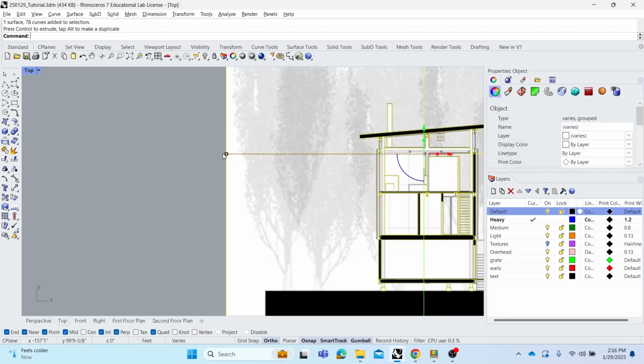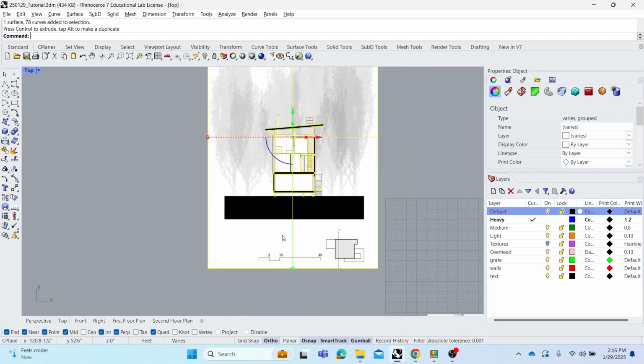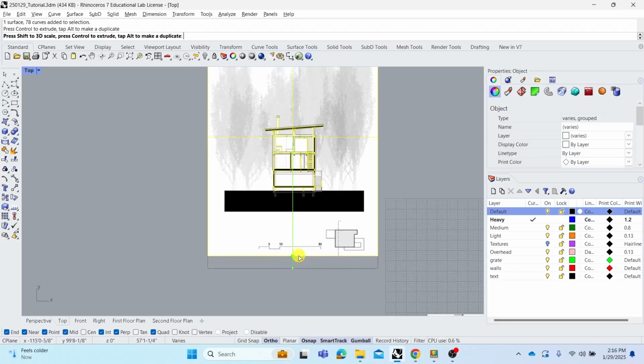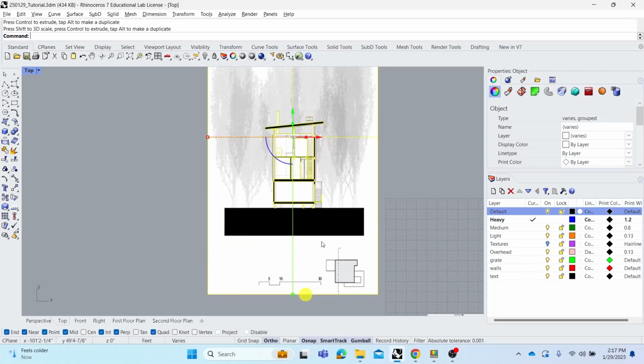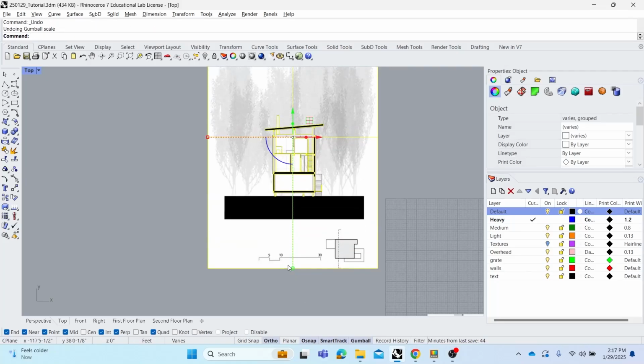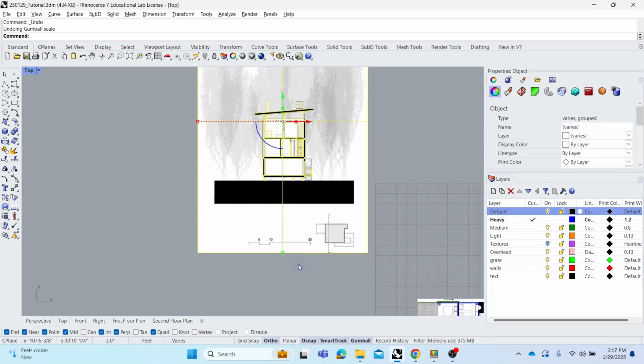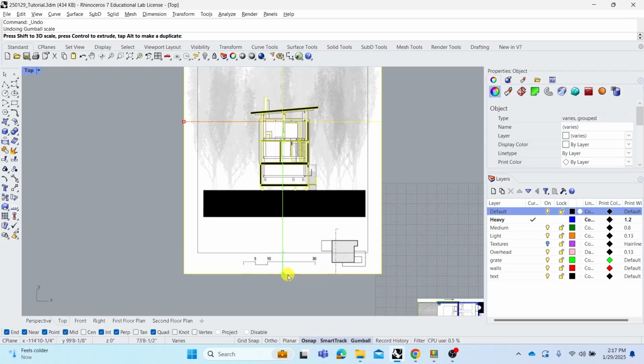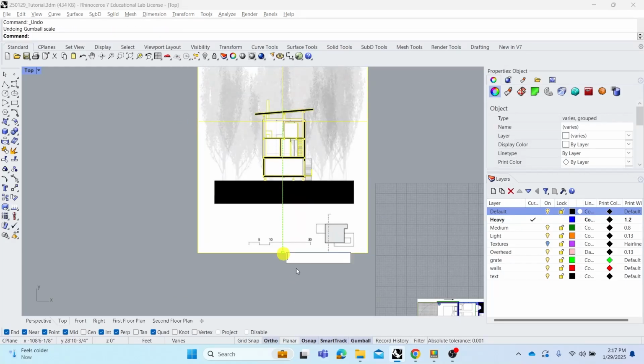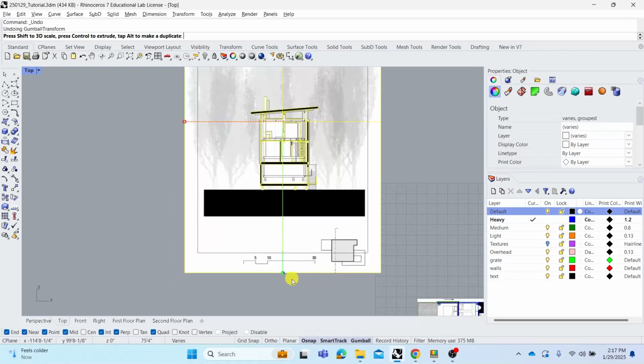Now, the squares on the outside perimeters, those are shortcuts for scaling. If you click one of them, again, you can type in the distance that you want that to be scaled, or you can drag it. And I can see that it's only dragging it in one direction, which is our scale 1D. If I want to scale things in 2 directions or uniformly against all sides, I can hold down Shift and drag this again, or tap it, right? And it will scale it uniformly against all sides.